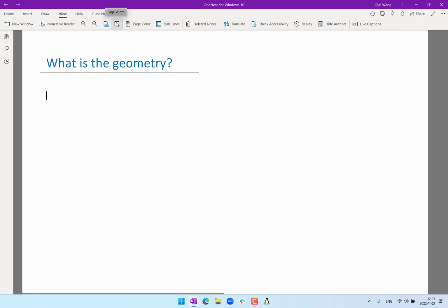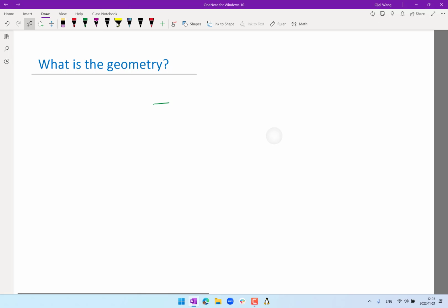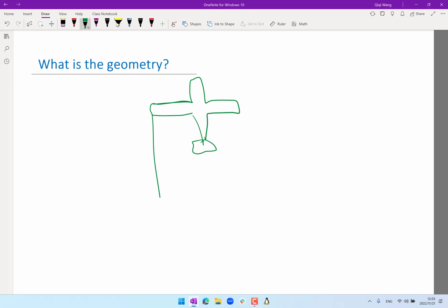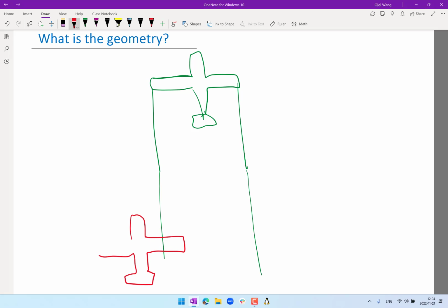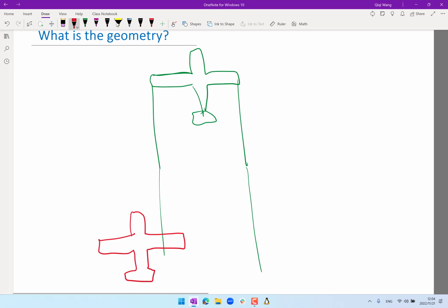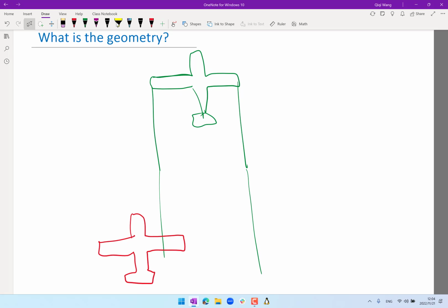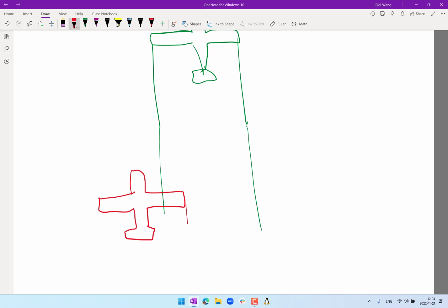So one airplane flies ahead, and this is the airplane that's ahead. The simplest assumption is that it has two trailing vortices. And assume we have a second airplane, say red, being towed. And the idea is that it probably offsets a little bit, so as to minimize the induced drag penalty. And that has its own trailing vortices.